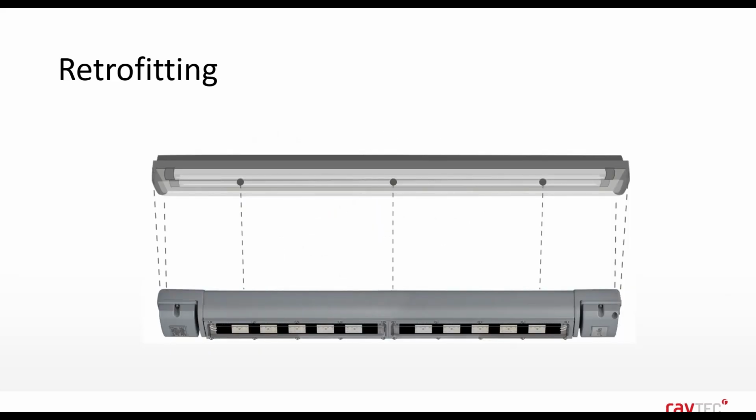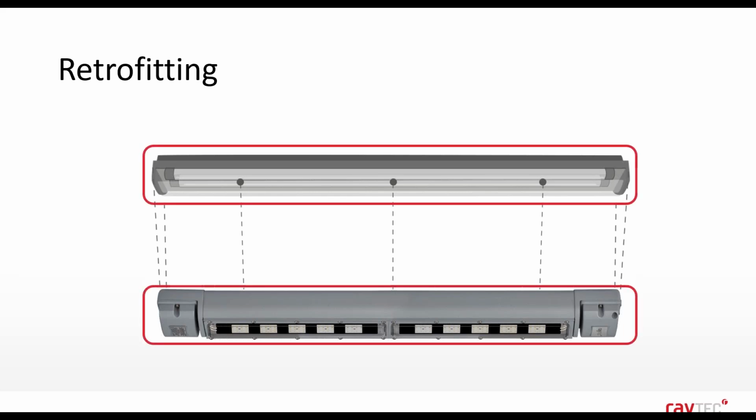If you are replacing old fluorescent fittings, you also need to give close consideration to the new luminaire's dimensions, cable entries, and its fixing centres. So we'll run through each of these one by one. So firstly, the dimensions. The replacement LED linear should be the same size as your existing fluorescent fitting, so traditionally 2 foot and 4 foot sizes. A replacement luminaire of the same size will mean that those existing cables that you might have installed won't have to stretch any further, so they can still be used on a new installation.